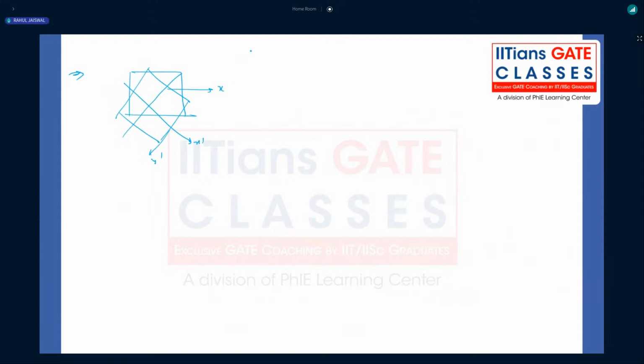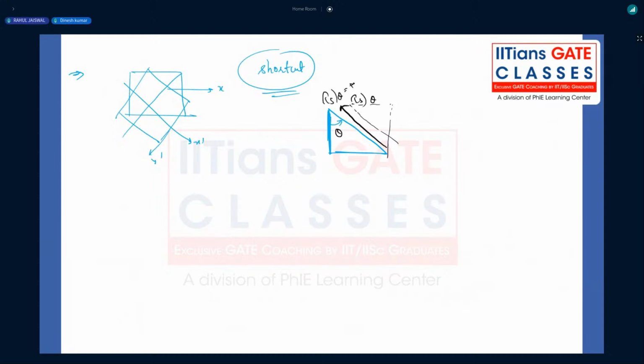So let me tell you the shortcut for the direction of shear stress. Understand? Whenever on any plane, remember what I'm saying. You know the conventional way, right? Whenever you are finding tau n theta on a plane inclined at an angle theta, like this, you imagine the other half of the plane which completes the state of stress condition on the other plane. On this plane, if it is tau n theta, our answer is positive.